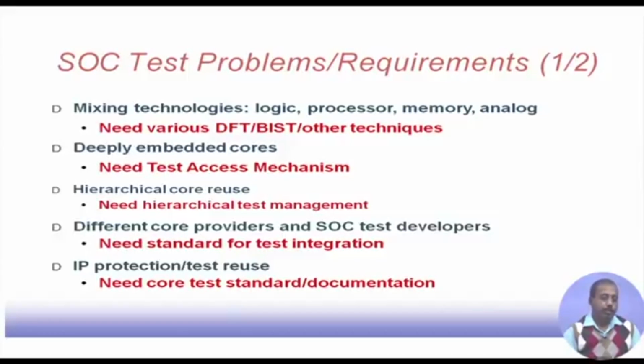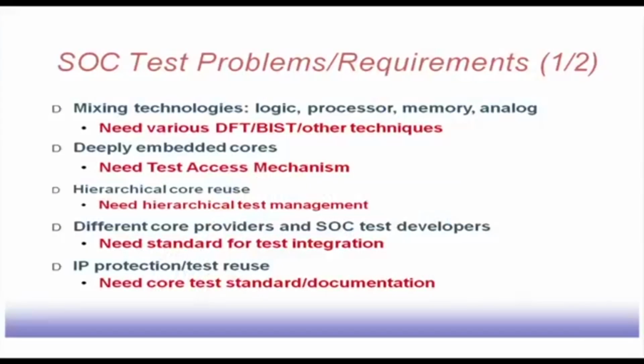Secondly, generation of test patterns is difficult, because I do not have the full detail of all these components. I cannot design an ATPG process so that test patterns can be generated for the processor unless I have the gate level netlist of the processor. Naturally, that stops an integrator from designing the test vectors or test technique for a particular component of this board, of this chip.